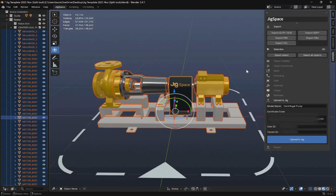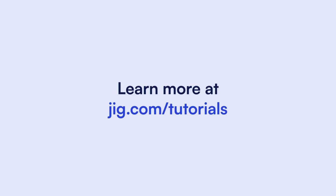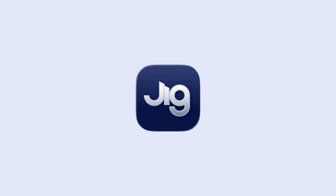Now, as well as being able to export your model, we also have the ability to upload a model straight to the Jig library using the Upload to Jig tool. For this, you'll need to enter your model's name, you'll need a certificate code, your user ID and the tenant ID. If you don't have these details available, you can reach out to customer success and we'll be able to supply those for you. And in order to do this, I just need to upload to Jig, and that's going to save my 3D model into the team object library. So not only will I have access to this, now all of my colleagues will also be able to access this 3D model inside of that Jig library.